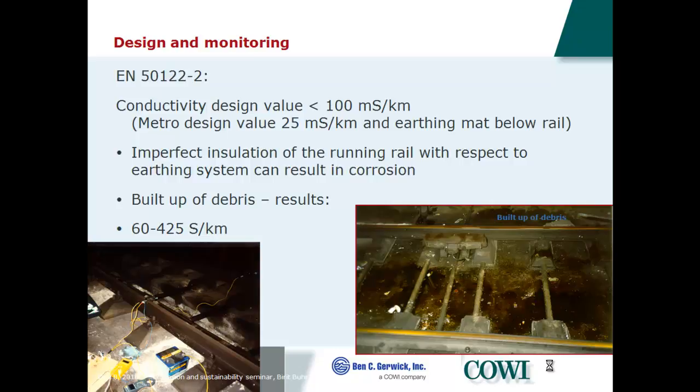Especially with all the city traffic that we have. There are different kinds of city traffic. There could be trams. If you talk about San Francisco, you have a tram system, they are direct current operated. So they could actually make stray currents by themselves, causing interference on other structures. So if you bring on a new structure, you really, really need to map where things are.